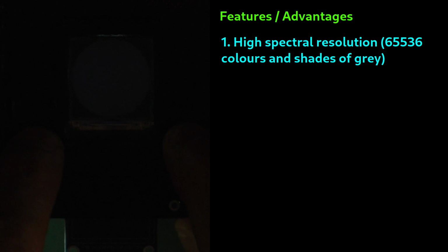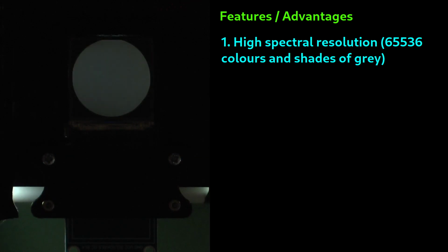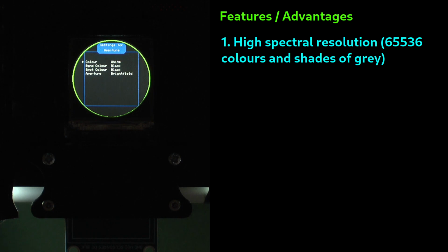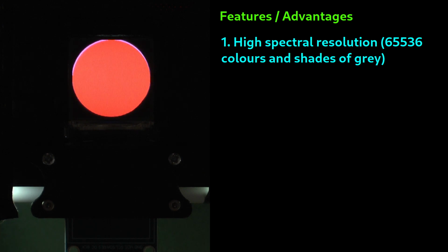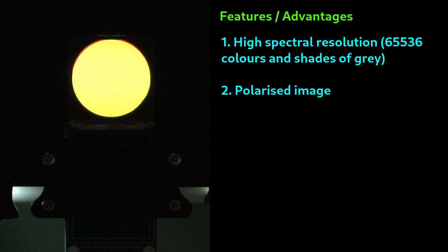The PUMA SLM is a color SLM in that it can restrict light passing through tiny RGB filters differentially at each pixel position, and it can restrict the light in a graded way, so not restricted to all or nothing passage like a traditional physical aperture. Because the PUMA SLM is based on a TFT screen, the light passing through it will be linearly polarized. This may be an advantage, a limitation, or a neutral point depending on your intended application.